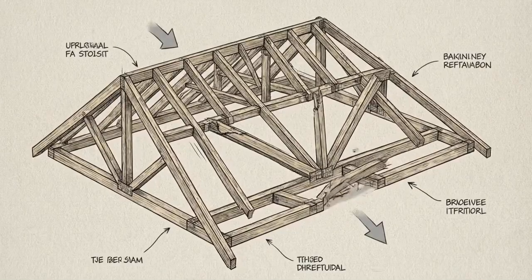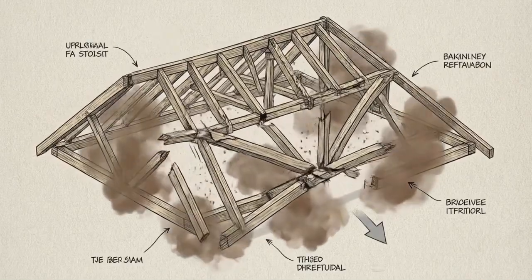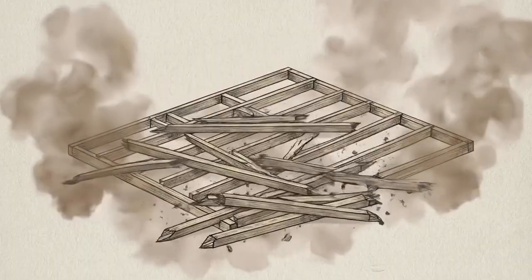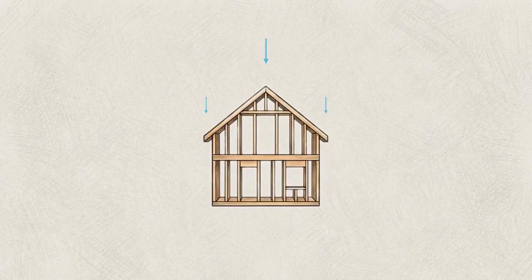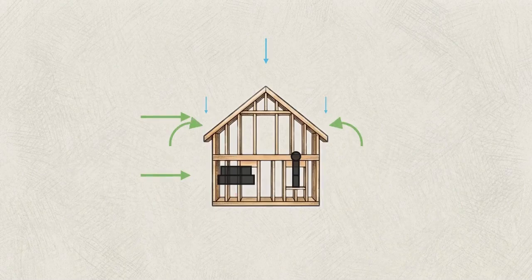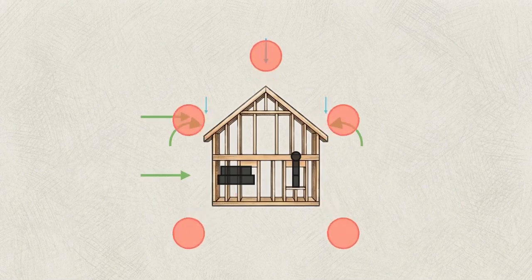Inside a residential roof space, structural members are under constant physical stress. Gravity exerts a relentless downward pressure. The frame must support the dead load of the structure itself alongside the live loads of occupants and materials. Simultaneously, wind creates lateral and upward uplift vectors that attempt to displace walls and separate the roof from the building.